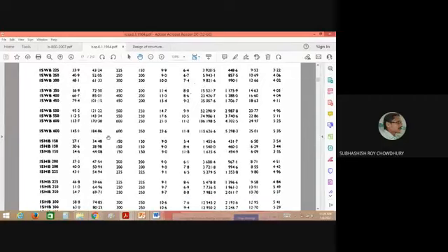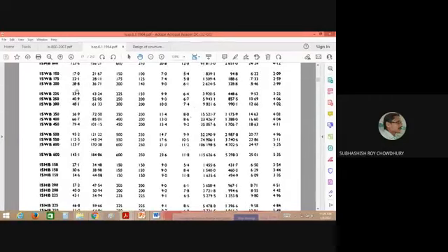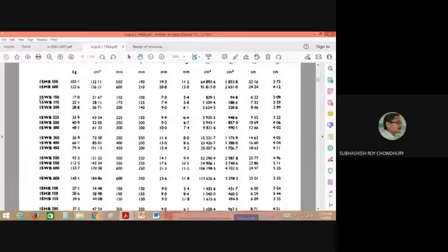And ISWB is also another section type, the wider beam sections. If you compare the width of the flange and the depth of the section, it is wider. So from that point of view, they have named it in this way.